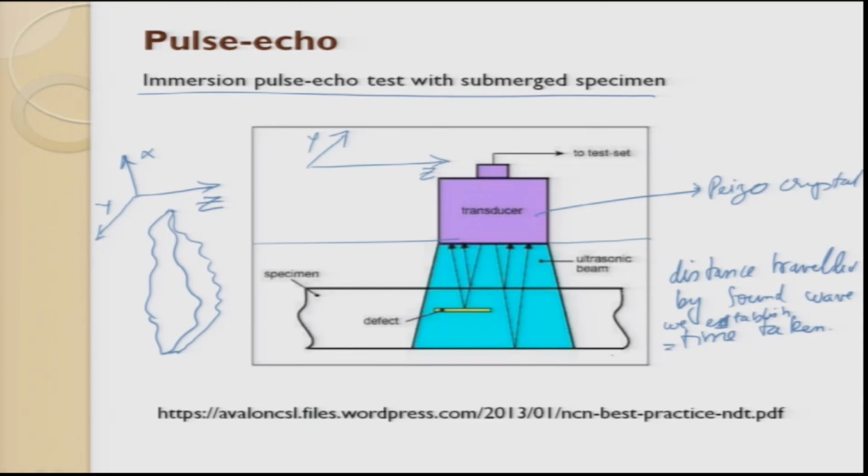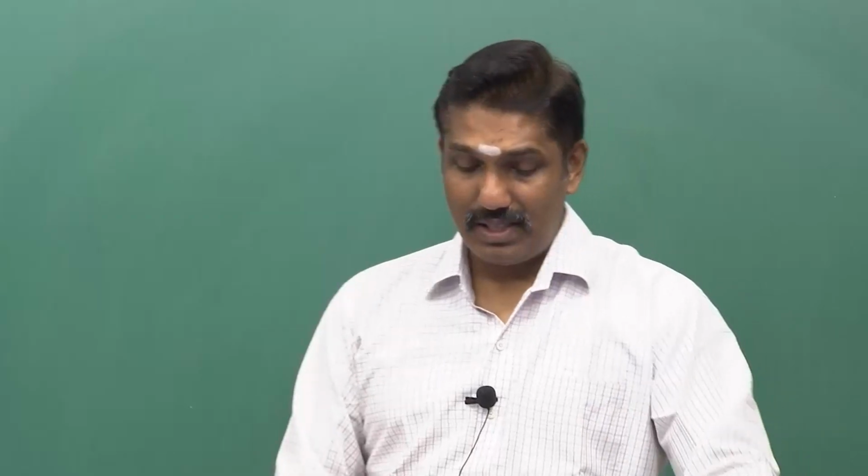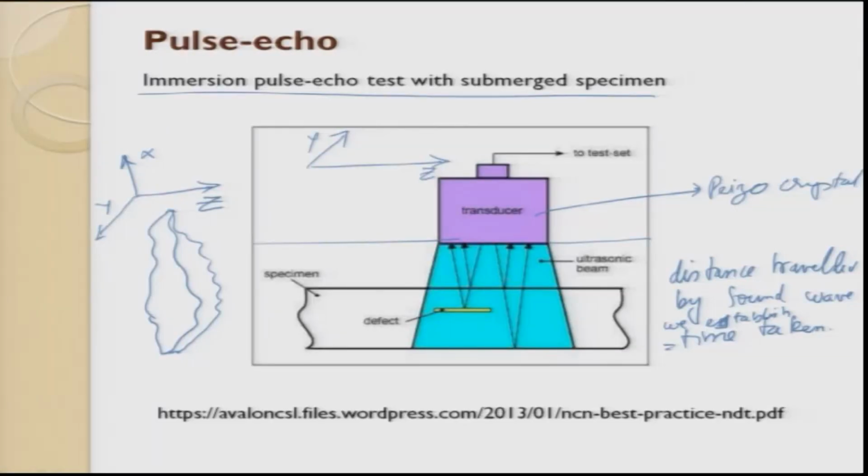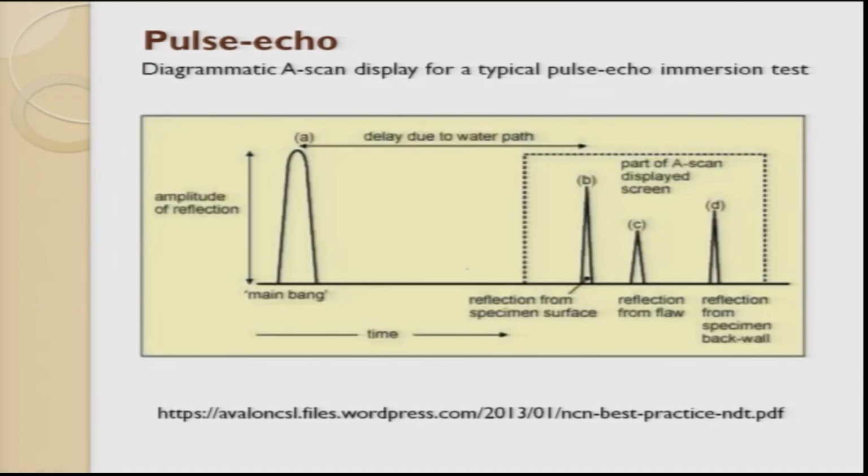Is it clear? Here it is called the pulse echo type, or people say pitch and catch. The sound waves are sent from here, go to the workpiece, and then get reflected back; it is one way. The same goes here and it gets reflected back, with varying time differences. If there is a defect, it goes back and you get this signal, so you can see what the signal looks like.